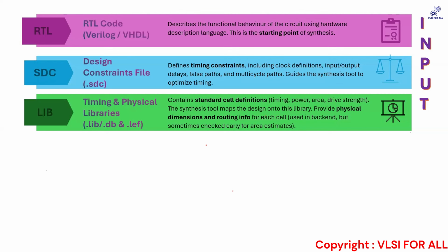It is not helping me out through my optimization, so I can restrict it by passing on don't touch or don't use. But as of now, when you're doing a synthesis, you cannot put a very hardcore constraint that I cannot use the cells, and whatever cells that you can use are present in the libraries.